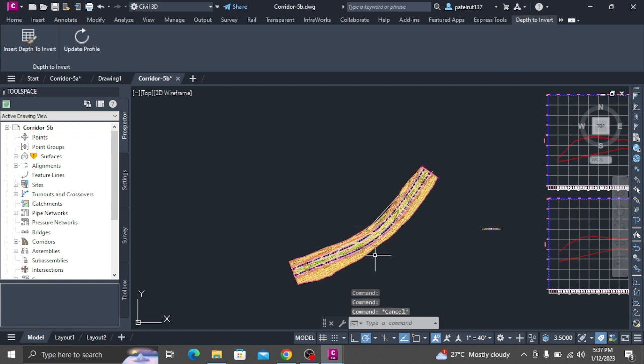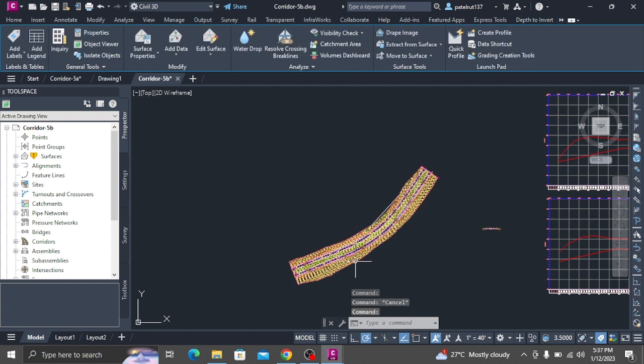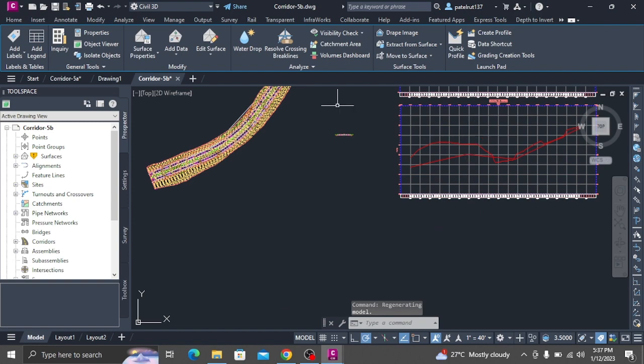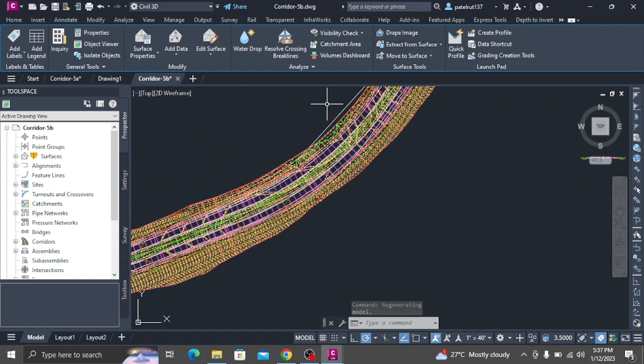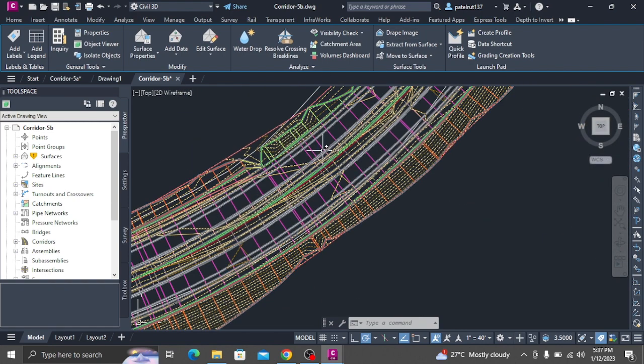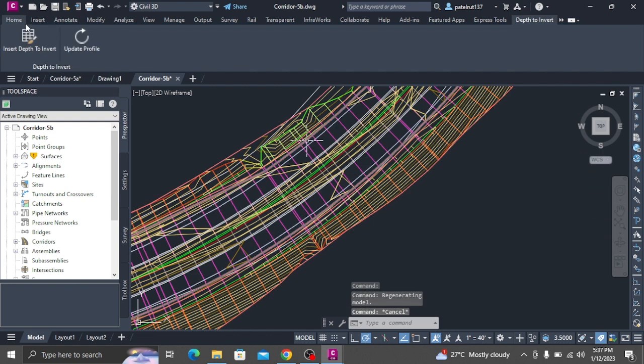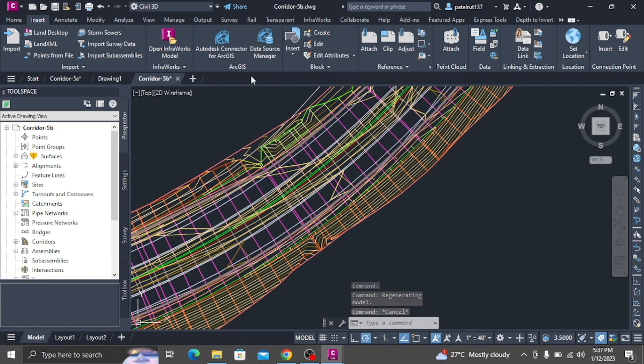In the Corridor Surfaces dialog box, expand the Corridor 1 Paved Surface Collection item to see the boundary item. Change the corridor boundary name to Pave Outside and set its use type to Outside Boundary. On the Boundaries tab, select the Corridor 1 Paved Surface. Right-click. Click Add Interactively.